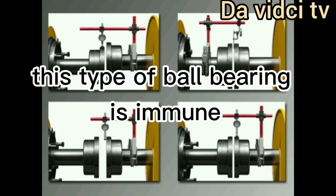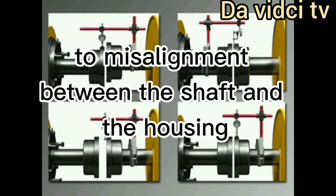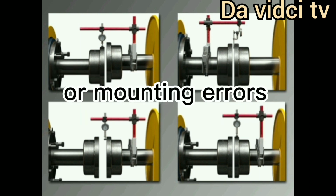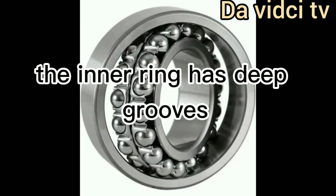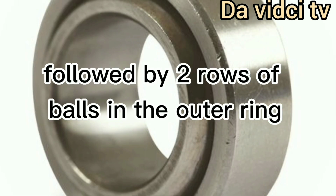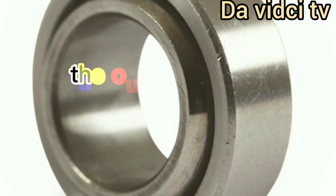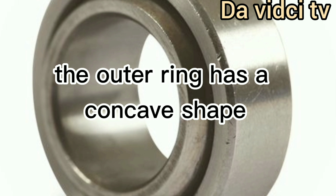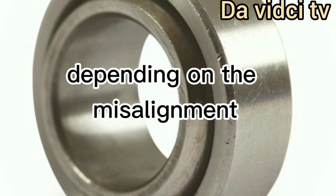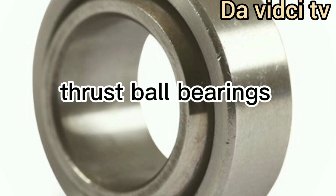This type of ball bearing is immune to misalignment between the shaft and the housing, which may happen due to shaft deflection or mounting errors. The inner ring has deep grooves similar to deep groove ball bearings, followed by 2 rows of balls in the outer ring. The outer ring has a concave shape, and this grants the inner ring some freedom to rearrange itself depending on the misalignment. Thrust ball bearings.